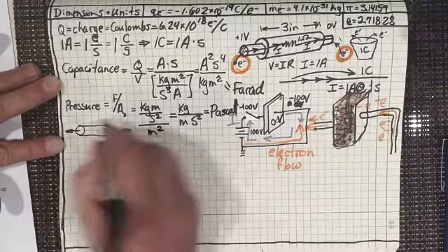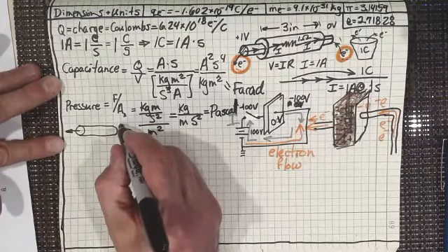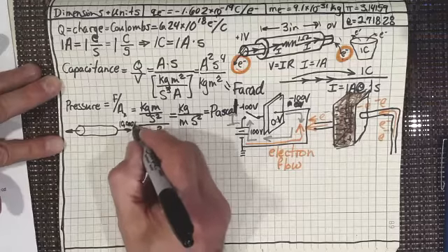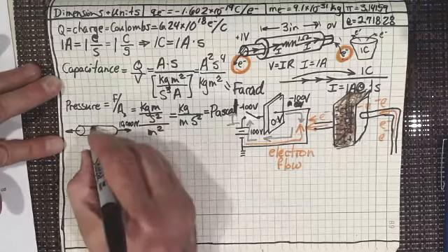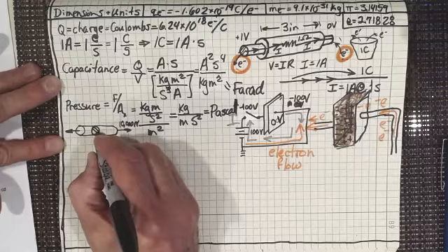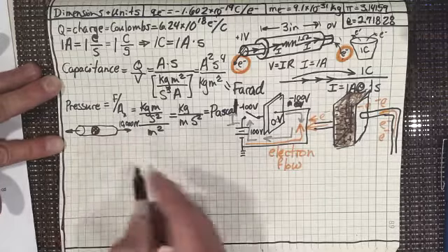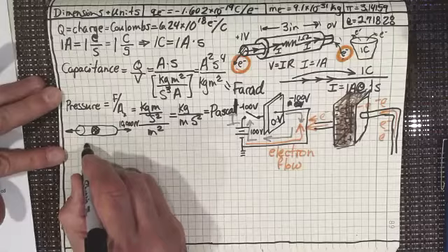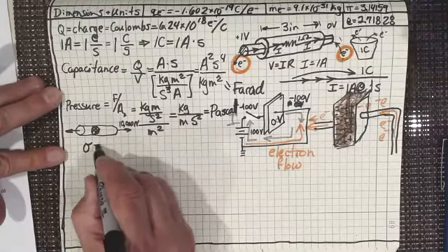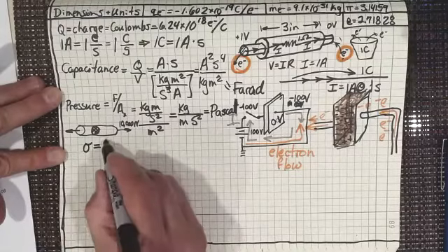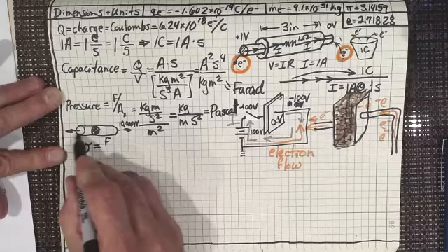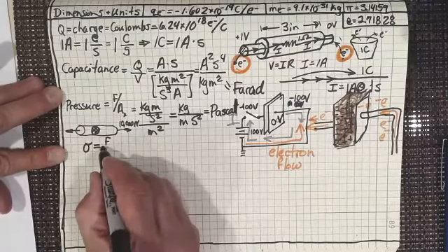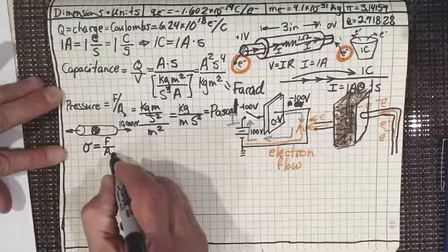Let's say that we've got something like 10,000 newtons that we're pulling on it with, and then we look at the cross-sectional area of that, we can actually do the same thing. We could say that stress, and we usually use sigma, is equal to the force in that solid piece of steel, divided by the cross-sectional area.